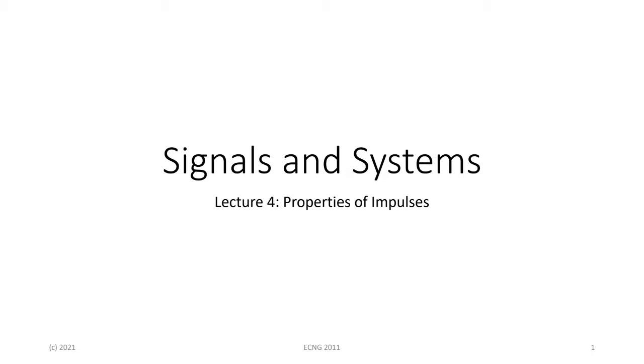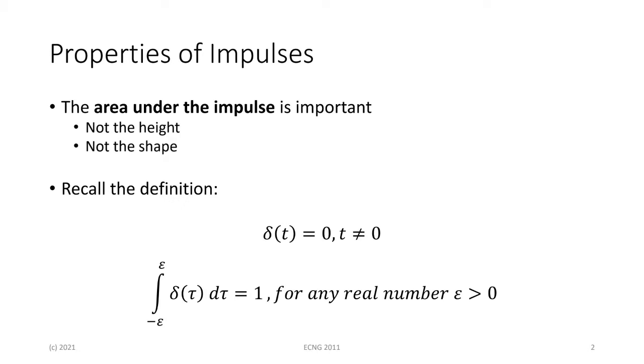So today we will be continuing with our discussion of these special signals that we started talking about last week, right? And of course that peculiar invention called the unit impulse. Now, strangely enough, you might be asking yourself, when am I likely to encounter something like that? It's defined by that bit of maths below there. It doesn't really exist in a practical sense because the area is one, yes, but the width is 0 and the height is infinity. So we define it as having an area of 1, and you could probably consider it like an energy of 1 if you like.